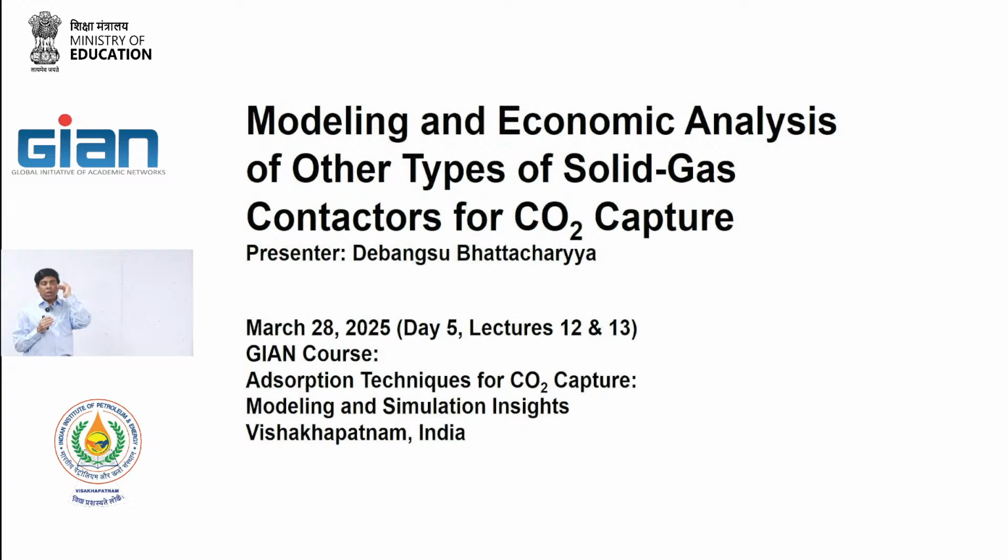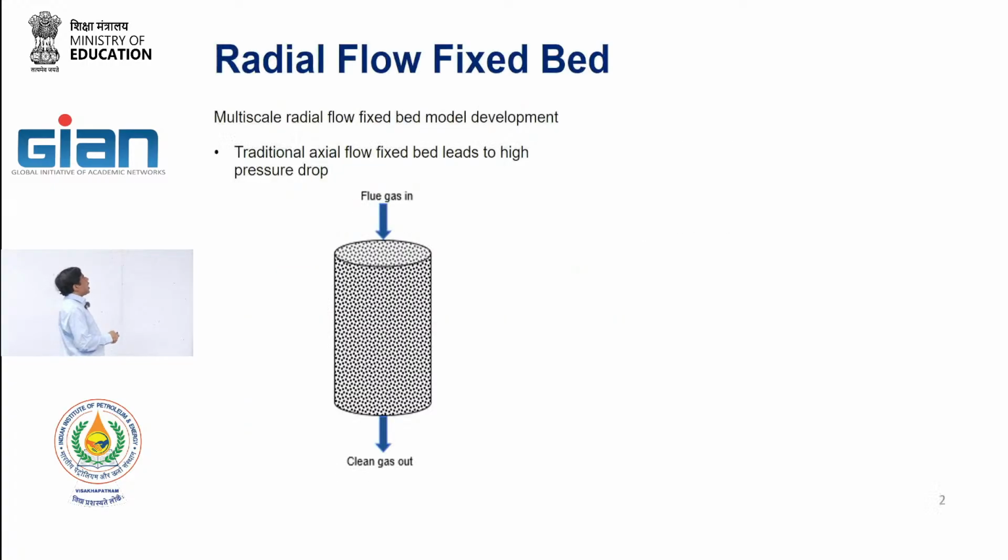Whatever is the isotherm that you got, based on the thermodynamics, the maximum loading, no matter what you do, you cannot exceed that, because thermodynamics is the upper bound that you can ever achieve. So always keep that in mind. I'm not saying that by doing this, you will be increasing the loading. No, you are limited by your isotherm, but we want to get closest to the isotherm.